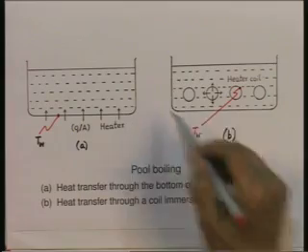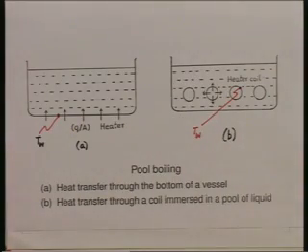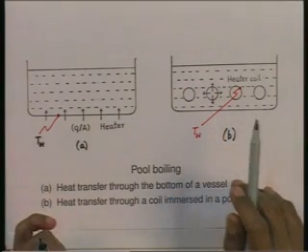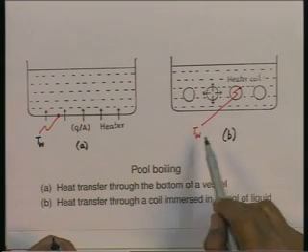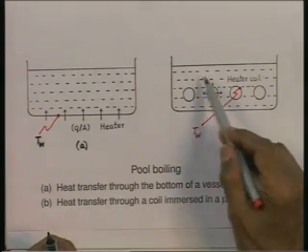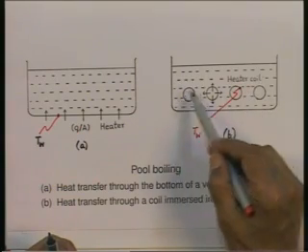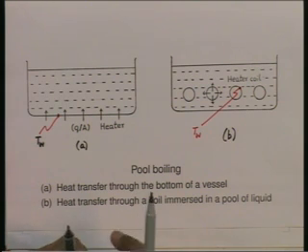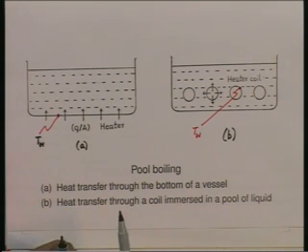And again the liquid is at a pressure, and the saturation temperature corresponding to that pressure is T s. Now, if T w is greater than T s, as we have said earlier, then it is usual for a part of the liquid surrounding this heated surface, either here or here, to change phase. That means, to go into the vapor form, and we call this boiling.